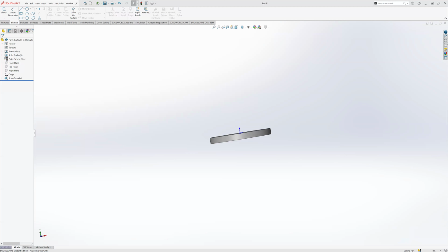So let's do the spring example. Okay, so we have that. Then what I'm going to do is use the same sketch. This is a very powerful tool in SolidWorks as well: the selected contours option within extrudes or revolves or any type of feature. A lot of features have this, but predominantly you see it used a lot in extrudes where you have several contours that you may want to extrude different depths or different shapes.